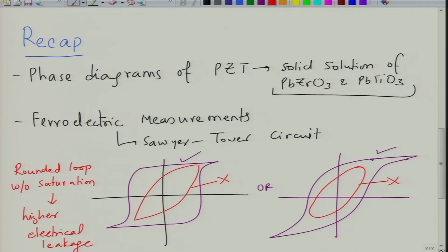As a result, often one needs low temperature measurements to distinguish between the ferroelectric contribution and the leakage contributions. Even at low temperatures, there is a possibility that you may not get saturated loops. So, you must be aware of what is good and what is bad, and do not report the bad loops as a ferroelectric loop. So, now let us go to the details of this lecture.